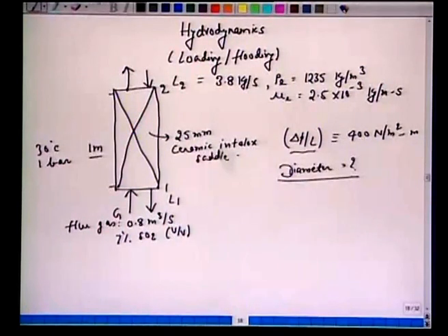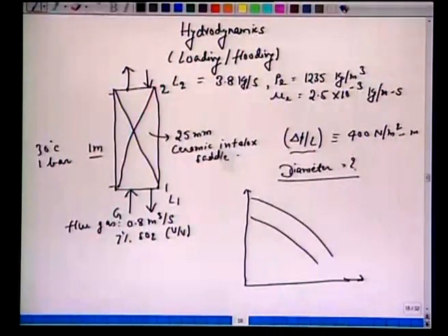All right. So, before we take up that graph, if you recall, we had this Eckert plot, later modified by Pickford, which we called the flooding and loading graph. You had these curves, and here we had certain quantities which we are supposed to evaluate.